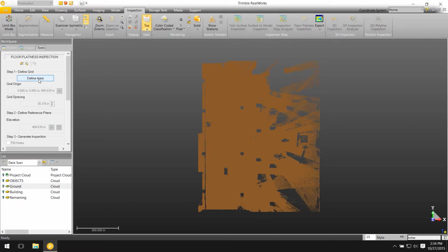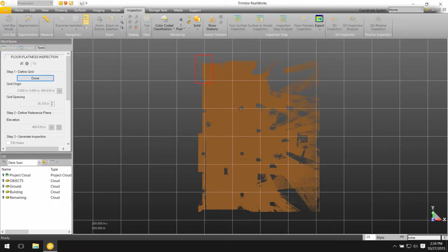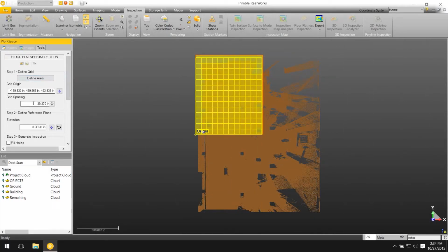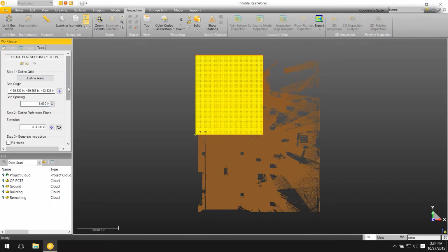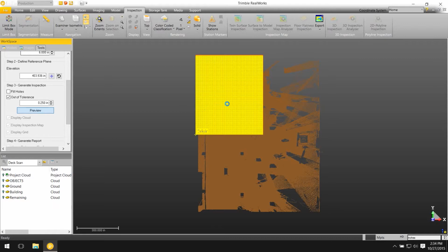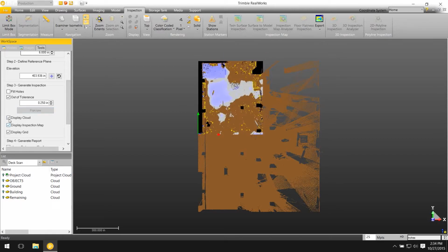So we can have a step-by-step process to get about 4 or 5 different deliverables out of this point cloud in relation to knowing if the floor is poured flat, knowing where the different variations of contours are, so I know where, hey, I might need to put some fill into it, or I might need to do some grinding to level out my concrete.